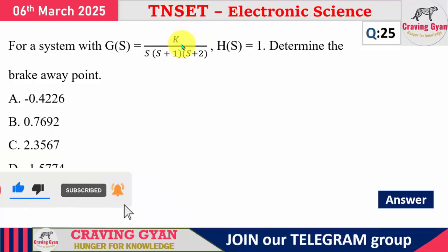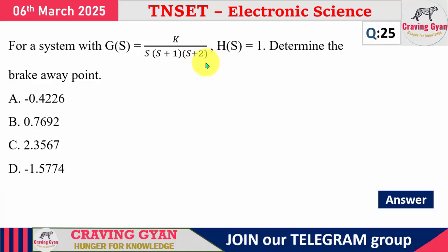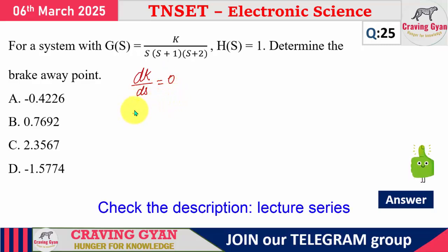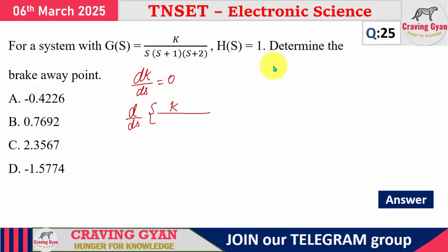Last question. G of s equals K divided by s times (s plus 1) times (s plus 2). What is the breakaway point they are asking? In order to find the breakaway point, dK/ds equals 0. Take the K value as 1 and solve. Here d/ds of K divided by s(s+1)(s+2), which I can rewrite as s cube plus 3s square plus 2s.